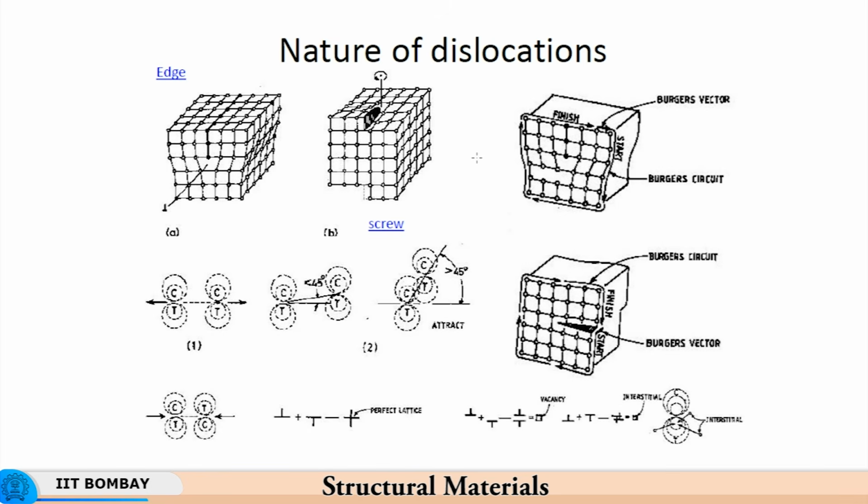On the other hand, if the two interacting dislocations come together on planes which are not separated with respect to each other. Here this shear plane and that shear plane are separated, but then they have an extra plane of this dislocation and an extra plane of that dislocation. So, there you will find that once the interaction is complete, they will leave behind an interstitial over here.